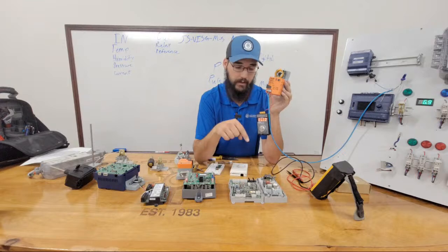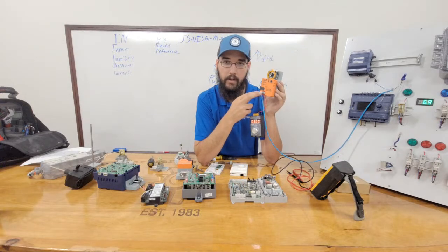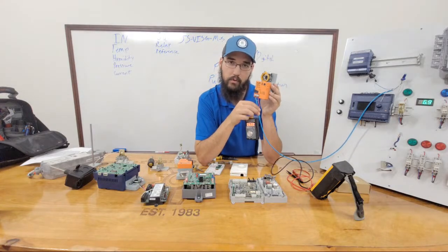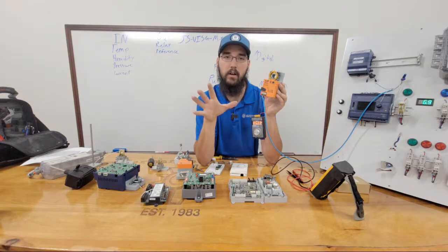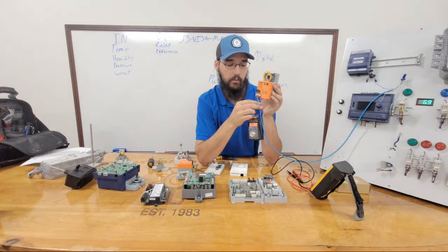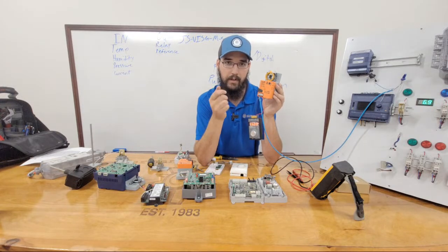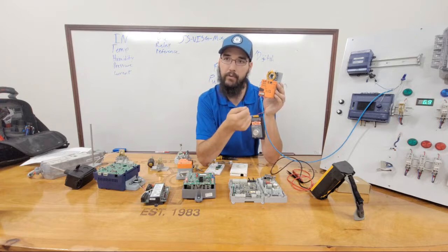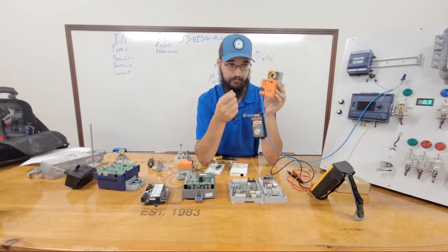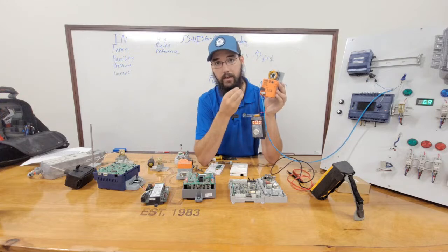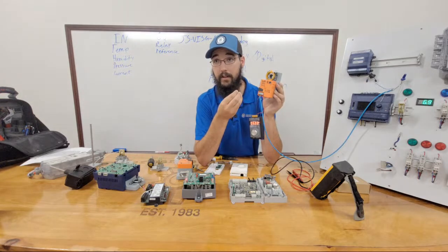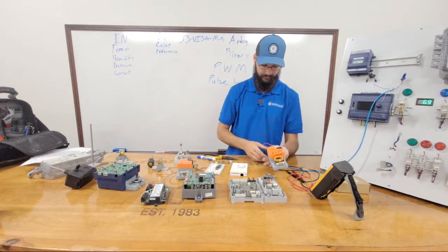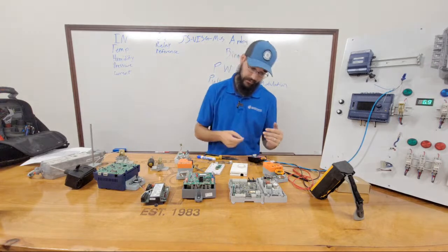So even if you read across there and you do not see it, take the time, go ahead and pull the wires completely off. Pull everything off. And then with it off, read between the common and the reference wires. And then see, okay, do I have the voltage I'm looking for? If the answer is yes,